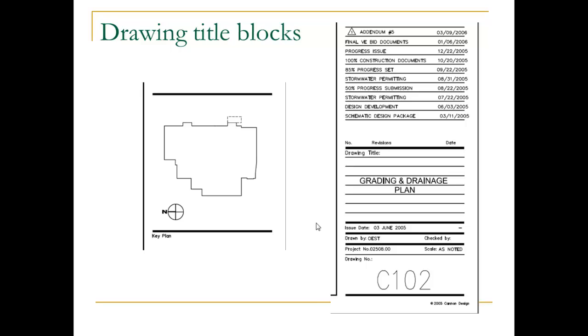One of the first things we're going to do is set up our title block that will be used throughout the semester. We'll probably do an 8.5 by 11 and maybe an 11 by 17 title block. It's important that we be as lazy as possible and still look productive. So we're not going to create a new title block for every assignment that we do. We're going to use a standard title block. We're going to work with some annotation text so that when it comes up, we just update the title and the scale, and some of the stuff will be automatically updated.